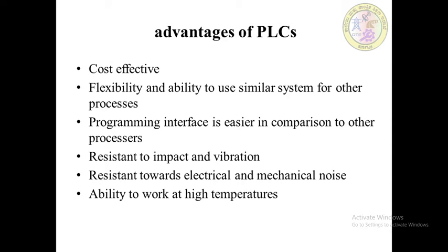Another advantage is flexibility and the ability to use a similar system for other processes also, meaning PLCs can be adaptive. It can be switched over from one program to another set of programs by changing programs only. If you change the program, meaning the set of instructions is changed, then the performed operation is also changed.